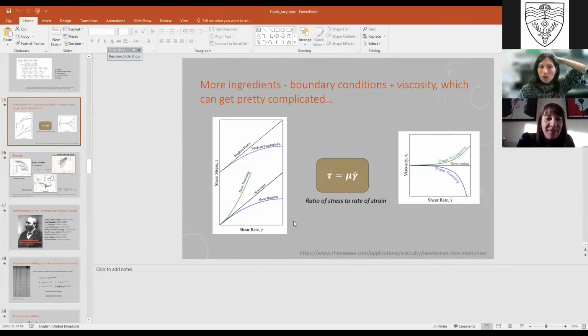Okay, great. So I was going to say, basically what you're defining is something like this shear thinning behavior, in which you don't have a constant viscosity. You may have a large viscosity when it's slowly flowing, somewhere here, but if it flows faster, or if you apply more stress to it, then the viscosity can drop. Generally, the inks are shear thinning because when you squeeze them through a nozzle, which is a contraction, you want them to lower their viscosity.